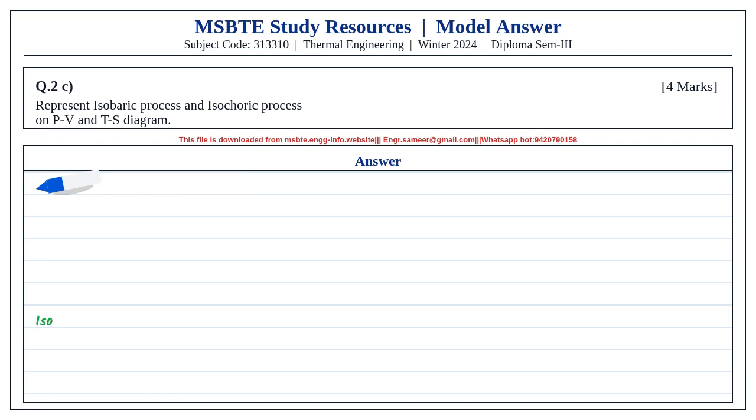Substituting this value, we get P1V1 by T1 is equal to P2V2 by T2, which is constant and equal to R. For mass m of gas, PV by T is equal to mR. Therefore, PV is equal to mRT, which is the characteristic gas equation.